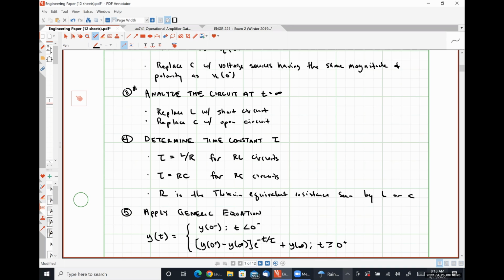Yes, sir. What is that before or after? So it's during the transient condition, because it has to be when the things are in a state of flux. The circuit doesn't really have a time constant for t less than 0 minus or for t greater than infinity, because nothing is changing, and tau effectively represents the rate of change for the system. So it's during the transient condition explicitly.